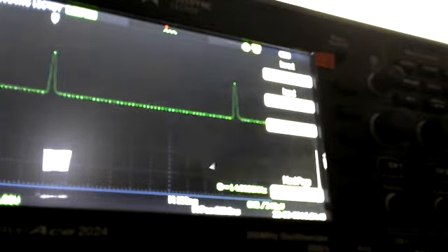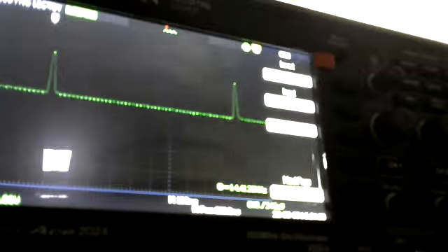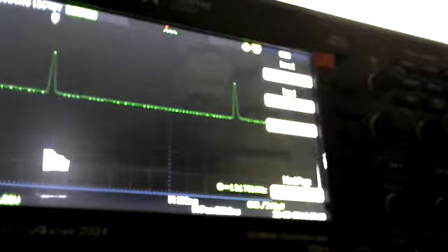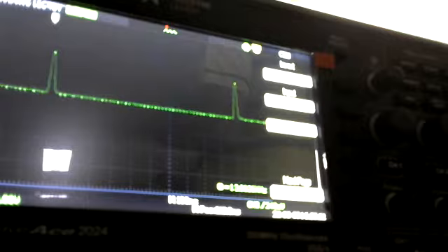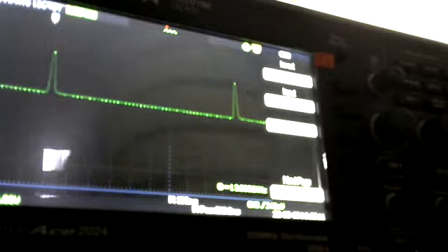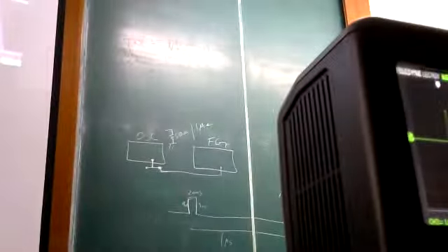Okay, so it's a slight digression here that instruments which are designed in this slightly intermediate frequency range will have this option. Even this instrument actually asks me, what is your load? Is it a 50 ohm load or is it a high impedance load? And actually it doesn't change anything. Its output impedance is always 50 ohms. It just tells you the number which you expect to see on the load. So let me just quickly explain that, and then we'll continue with the demo.